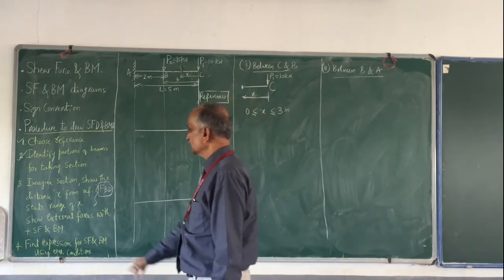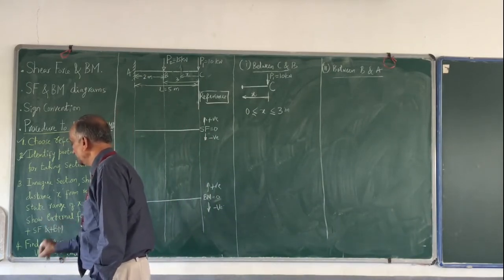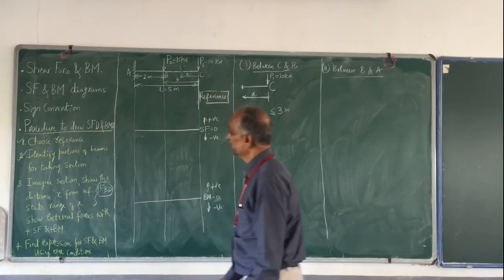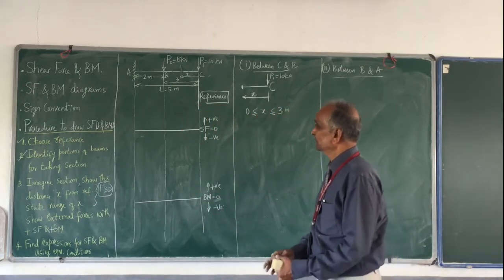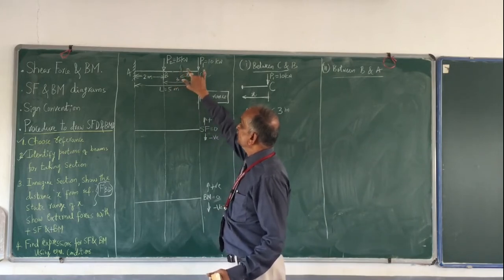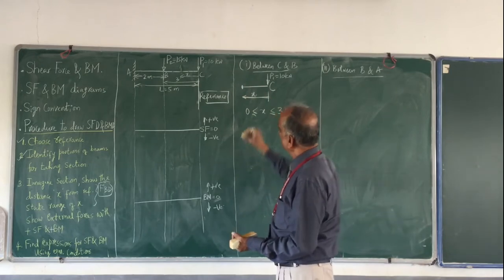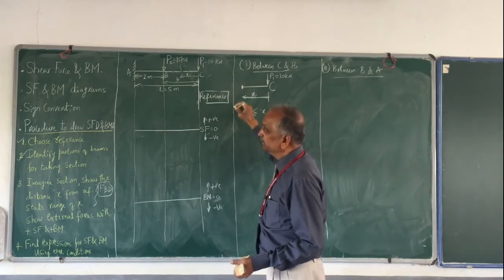Along with this, you also show the positive shear force and positive bending moment. Now this is where you have to be careful. I have taken a section here, and I have considered the right hand side portion for the analysis. So this is where the section is.